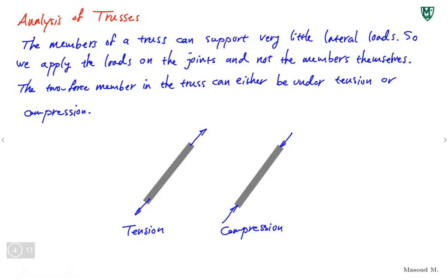Sometimes explaining too many things makes it more confusing. Let's just dive into how we can actually analyze the trusses. Right? The two methods: method of joints and method of sections. We're going to spend this week on method of joints and see how we can use that. And next week we're going to be more focused on method of sections. Now, method of joints is more related to equilibrium of a particle in two-dimensional space. Exactly whatever you learned there, a lot of it you're going to use here. Equilibrium of a particle in two-dimensional space, that's the main ingredient of method of joints.